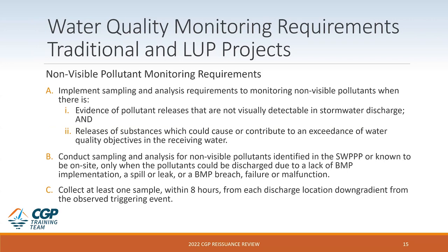Non-visible pollutant monitoring requirements. If there's a breach or a spill, we have to implement our sampling and analysis requirements for those non-visible pollutants, if there is evidence of the pollutant, and if those substances could cause or contribute to an exceedance of water quality objectives in the receiving water.